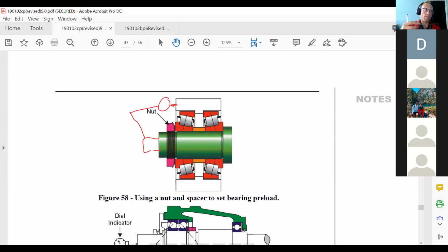Now, does a bearing with end play have rolling resistance? Of course it does. You can't ever remove all of it, but there isn't any additional rolling resistance because of the preload. Hopefully all that makes sense. So the pushing in and out of it, we wouldn't be able to measure it because whether it's at 1 pound of preload or 100 pounds of preload, it's going to have 0 end play, which is what you're measuring with this setup here. So what you would do, just like whoever said, a fish scale, perfect.